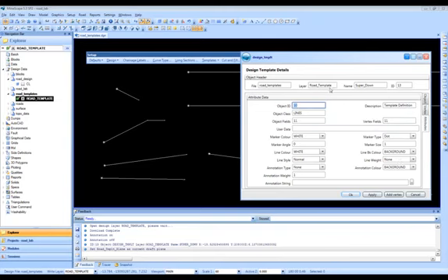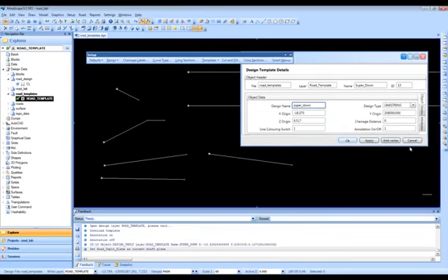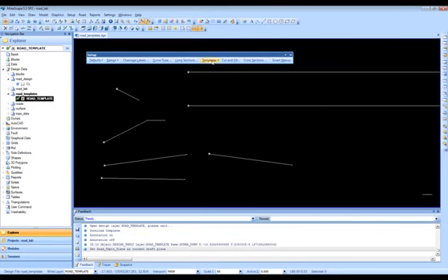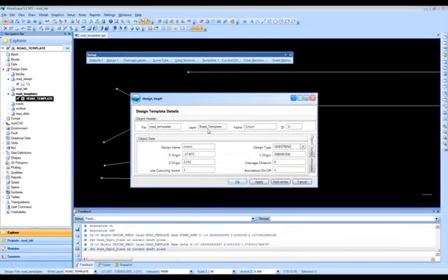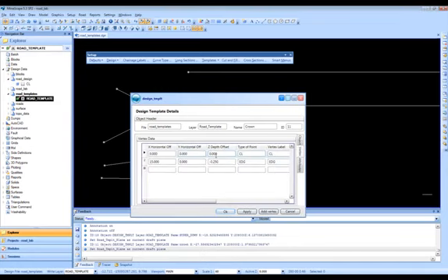And you can also set up some of the attributes for these things as well. So these are the road templates. This is a super elevation. And then I also have this, which is basically for a crown road. So this is basically the cross section. I want the road to slope off to either side for drainage, and so that vertex has a little different, not as steep of an offset as the other one.